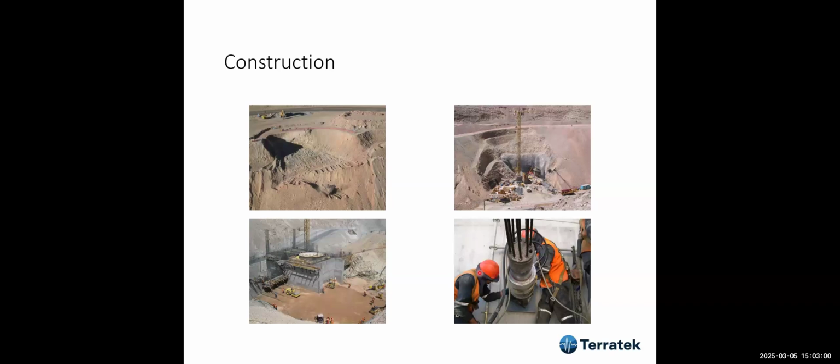And these are some pictures of the wall being constructed. In this case, we were not very much concerned about corrosion. And why? Because this is a very, very dry area. The average annual rainfall is about 3 millimeters only. So no corrosion problem, okay? And this, of course, won't last 20 years. This may last 10 years, more or less, until the mine is finished. So we didn't allow very much for corrosion because of this situation.